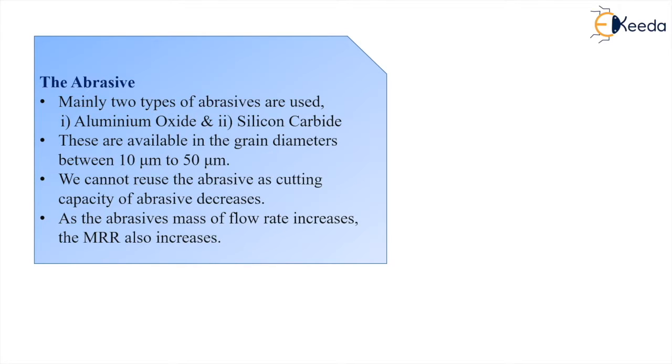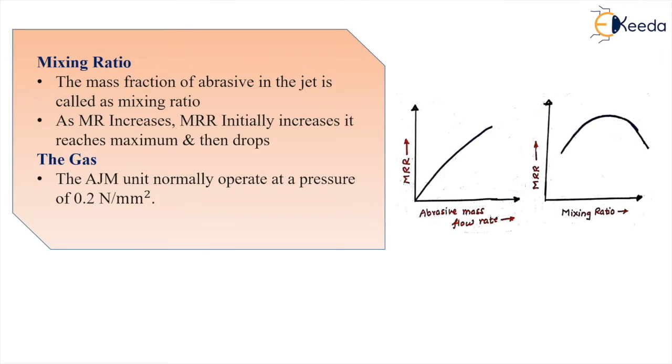So how do these abrasives have an impact on MRR? As we go on increasing the mass flow rate of these abrasives, definitely the material removal rate in AJM goes on increasing. See here, as the abrasive mass flow rate increases, MRR also goes on increasing.